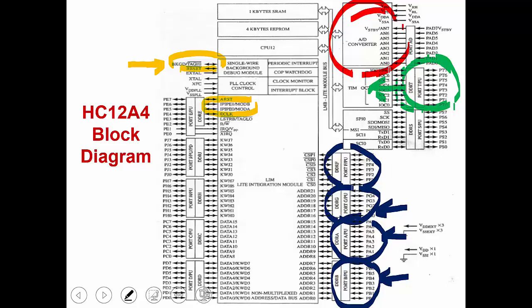The A to D converter system's corresponding register is called the A to D control register. We do have such a register at memory location 0062, the memory location whose address is 0062. That's a memory mapped register.